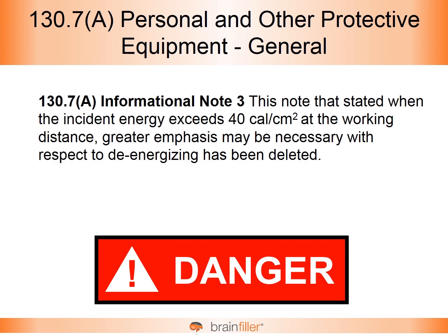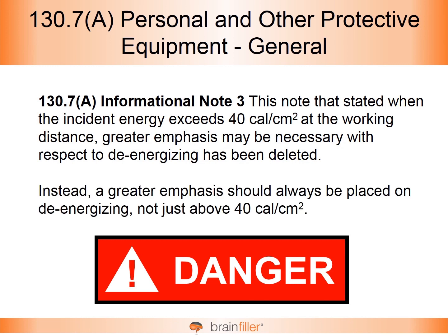And so this informational note was actually deleted, and for good reason, because instead, a greater emphasis should always be placed on de-energizing, not just because the calculated incident energy goes above 40 calories per square centimeter.